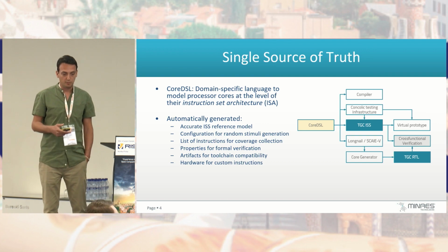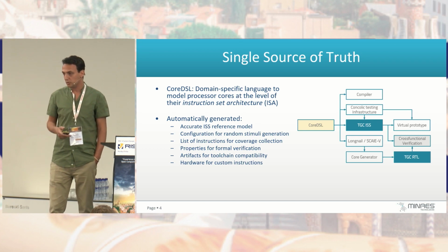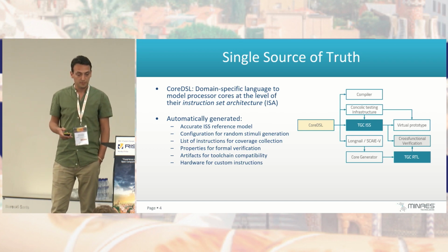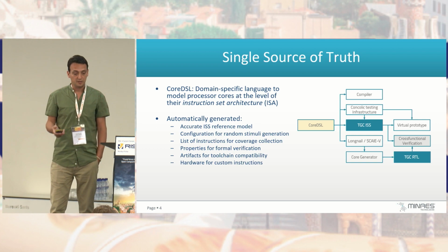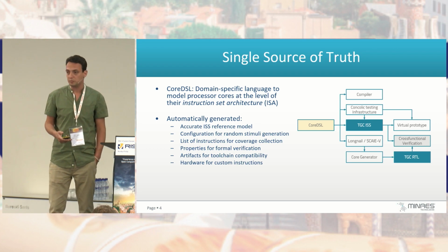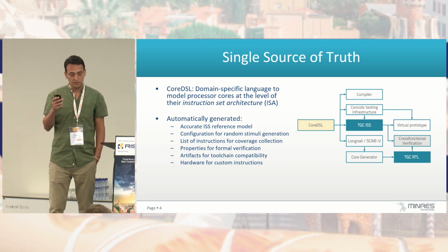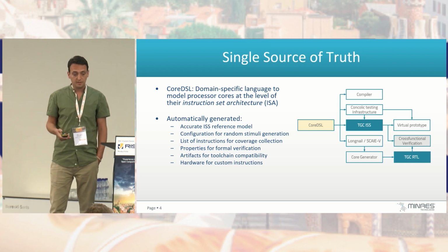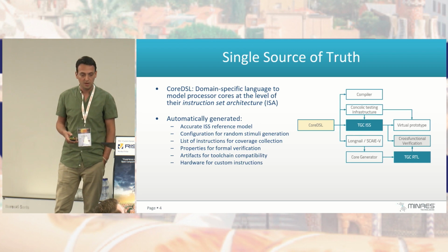For example, the full-blown instruction set simulator, but also configuration files for test bench elements, properties for formal verification, artifacts for toolchain compatibility to enable the usage of custom instructions by the target firmware. And last but not least, with assistance of HLS tools, we create hardware for custom instructions and seamlessly integrate this hardware into the existing microarchitecture of the TGC core.